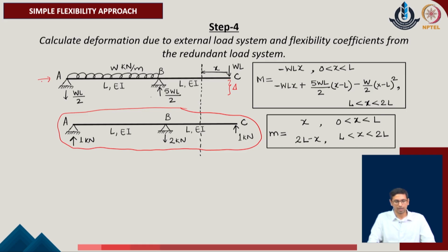So, we can consider that this is the real system with which we are evaluating the deformation at the given point, and to evaluate this displacement we are taking help of a virtual system in which we have applied a unit load in the direction of the required displacement. And while doing the virtual system, I will also be able to identify the flexibility coefficient of the given problem.